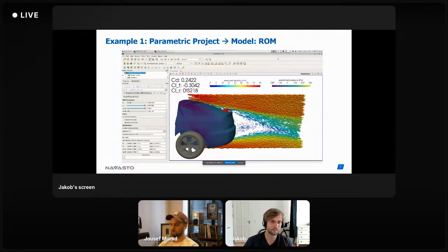But if you use such a simple method like a reduced order model, which uses a POD method coupled with an interpolator, you have certain requirements which you need to fulfill. And one thing is you need a consistent parametrization all the time. You cannot simply add or delete some of the parameters. And you also need a consistent mesh to make these 3D predictions here.